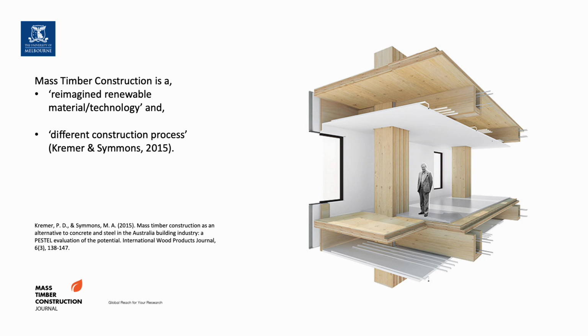And it's important to remember it's not just the material type, it's also the process. The process of prefabrication is what gives mass timber its competitive cost advantage and time and speed advantage edge. In terms of the material, its lightweight, its stiffness and its strength capacity differential based on the dimensional depth of the material is another reason why you would use it, and it's lightweight. It's a quarter of the weight, or 20% of the weight, of concrete.